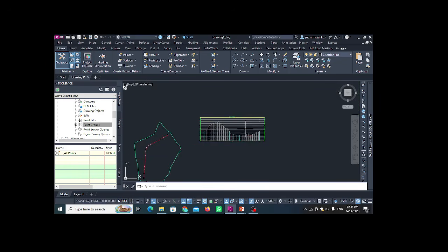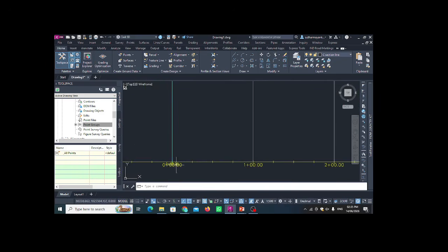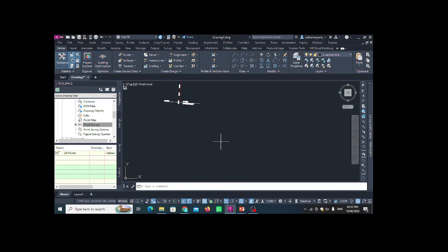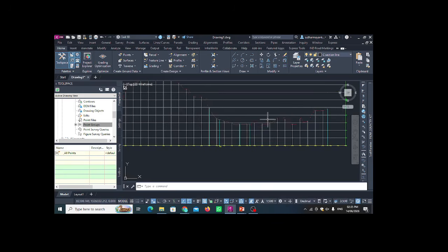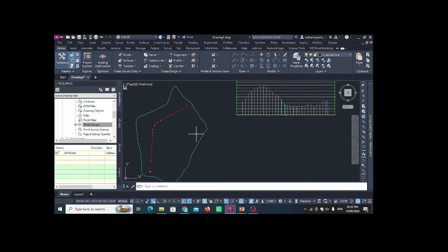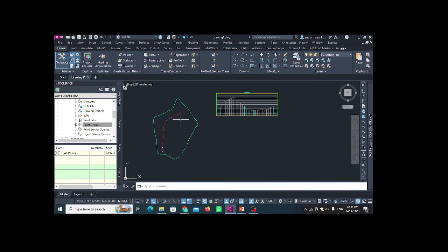Now here you can see, this is our starting range. So our starting range is here. Here our ground is at the top, and in this part you can see our elevation is far below this. So what happens here? If you draw the alignment straight through this, we have to face some issues of cutting and filling, lots of cutting or lots of filling. So here we have to manage all those things.